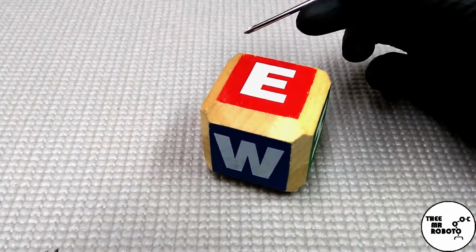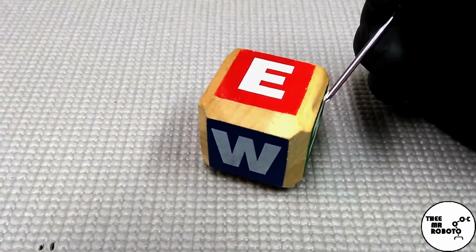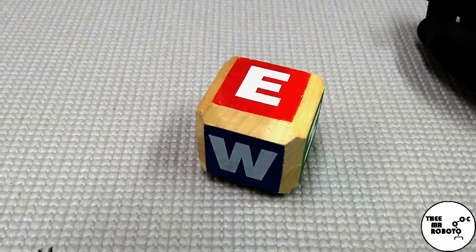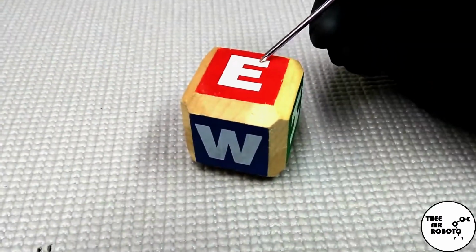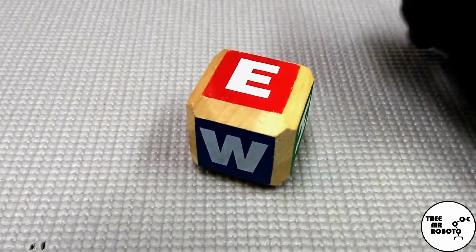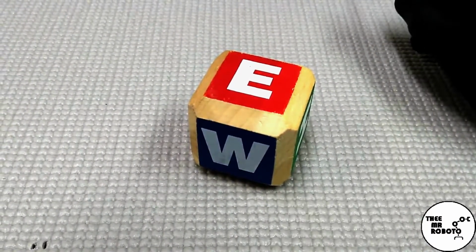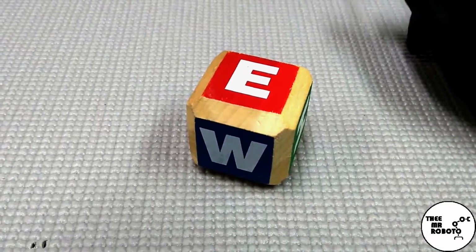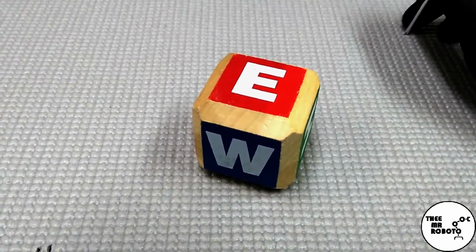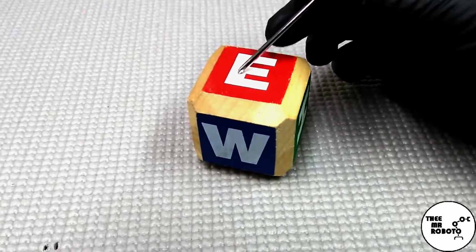And that's no good, because you spent all that time creating this beautiful letter E, and that's all changed now. If you would have used a base coordinate system or a work coordinate system, you could have eliminated the need to go in here and reteach all of these positions.